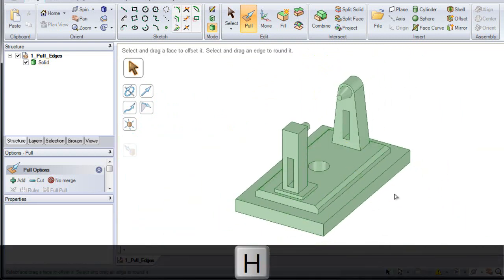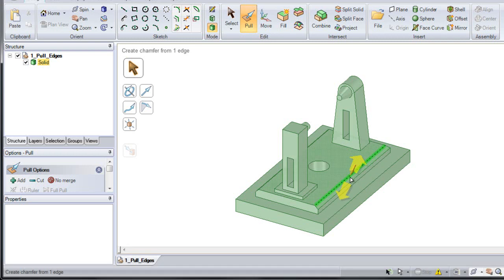So in this section, add chamfers to the top edge loop, offset to create the base, use copy to create this little box, remove the chamfer property, and try pivot.